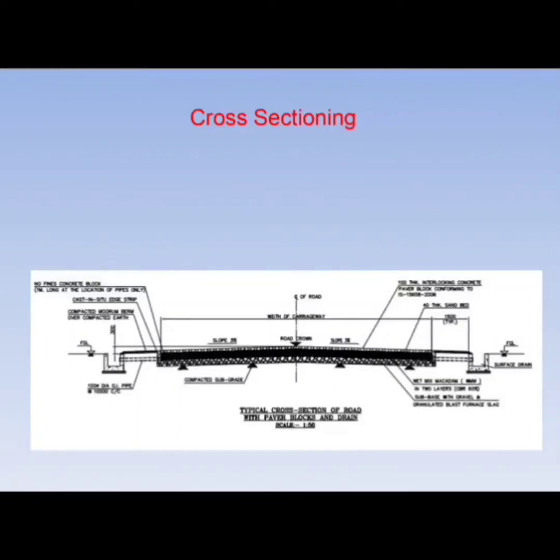Cross-sectional leveling will be carried out when levels are required in the transverse direction also. At every 30 meters interval, cross-sectional leveling will be done.